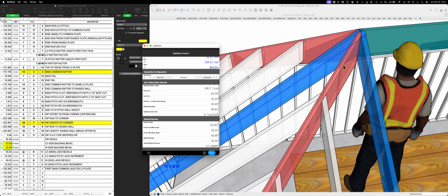The easy way to do this is get your table saw set to 23.09. Make sure you get that 09. Then just run this through the table saw so that the blade cuts from about the middle and whatever the bevel is. Then flip it end over end and run it back through so you have this diamond cut all the way along the top. That'll just make your life easy.